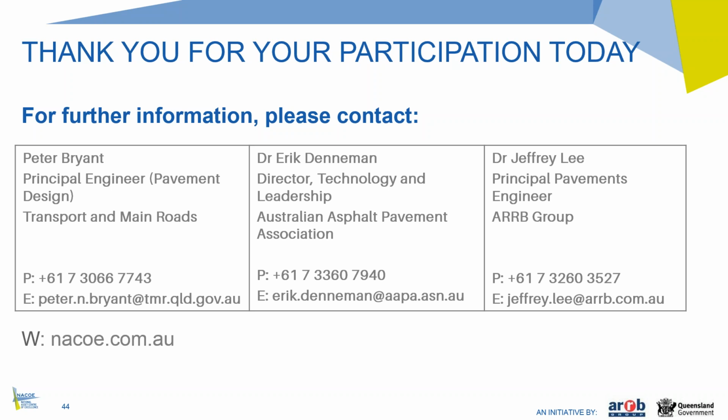The answer to that is not as a matter of course. We have been doing this as part of this research program, and actually the Austroads report shows very well how well the modulus that is achieved in the field correlates to the modulus that's achieved in the laboratory, and that is really a function of the conditioning method that is part of the Australian design system. So laboratory specimens are conditioned to reflect what's happening in the field, and I think it's actually quite successful at doing that. So that is work that must have been done many years ago when they introduced that method of conditioning.